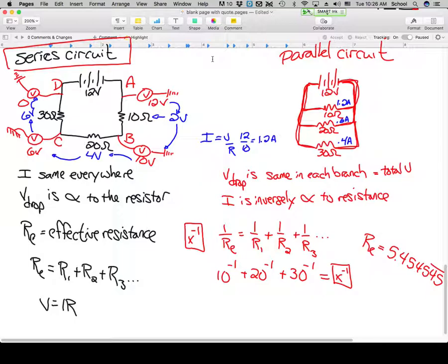Okay, 0.4 amp is going to be how much current goes through all of that green wire, right? And 0.6 is going to be how much goes through just this branch. And 1.2 is how much goes through that branch. But how much is going to go through this one or this one? That's going to be 1.0, because this one has to carry the current that goes through this loop and the current that goes down. Both of those go through this section, right? So if we add up those two numbers, that gives me 1.